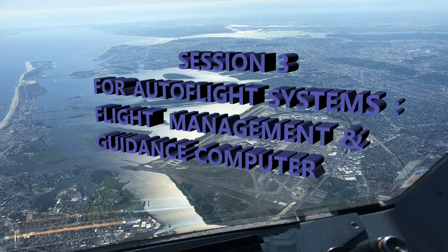You've got your main menu, as far as seeing what's available as far as the information or reports. Functions of the system that you have in the menu mode are going to be your last leg report, previous leg report. This is typical stuff. Your troubleshooting data. You also have your AFS test, your LRU identification, and you also have ground scan. So, last leg is on the ground only. Again, on the ground, you've got the previous leg report as well. It's going to show two types of faults: the internal and external faults that appeared in the last 64 previous flights. So that's all stored in there, and you're able to view that.